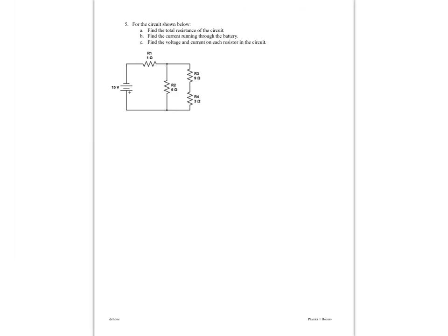All right, for this last one, we want to do a full circuit analysis of this particular circuit. So with this, we want to look for simple combinations of resistors, combine them, and slowly simplify the circuit. So first combination we're going to have is R3 and R4. Since they're in series, we're just going to add them, 9 plus 3. And so R3,4 gives us 12 ohms.